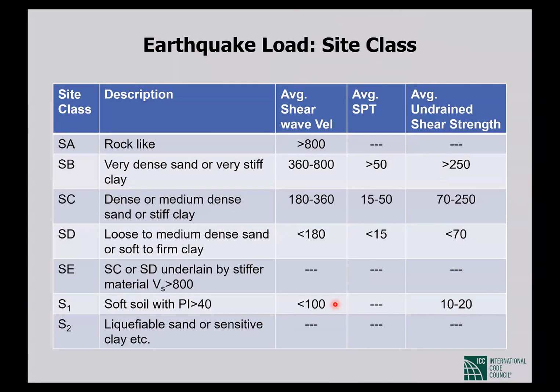Now, let's talk about earthquake load. Again, it is different this time. The method is completely different from the previous version of the code. But unlike the wind load, this is not exactly similar to ASCE 7. There are some differences, but at the same time, there are ways where we can simply use the software in a similar way. We can just choose ASCE 7. Those shortcuts are also given in the code.